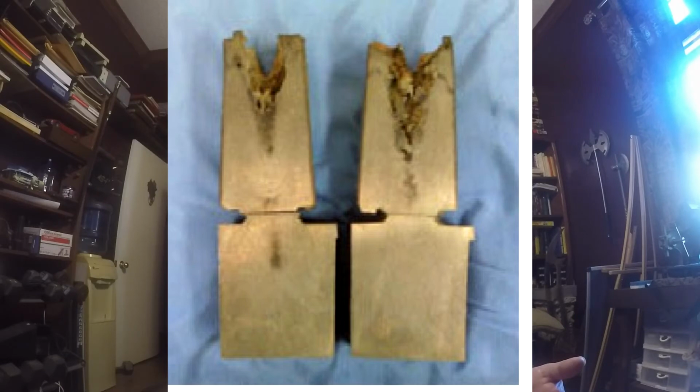Now the casting on the right hand side looks like it was well fed. Despite that neck right there, I wouldn't have had that neck there, but they must have put it there for ease in removing the riser, or maybe that's some kind of platform or a boss that they had to have as part of the casting. A good contact with the riser is absolutely essential, and there's no use in having a large contact if you have a tiny neck.